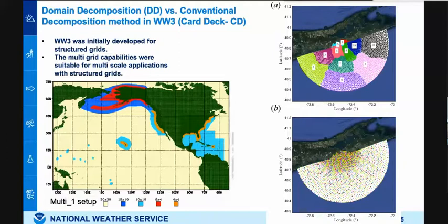And the old parallelization algorithm was still used by the model for this. But there were some limits, like the number of grids, so we couldn't go beyond 2 million unstructured nodes. And then the scheme on the structured grid was still explicit, so we had some limitation in terms of Courant number and CFL constraint.